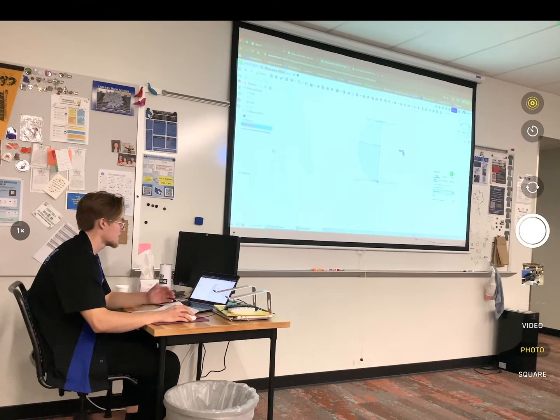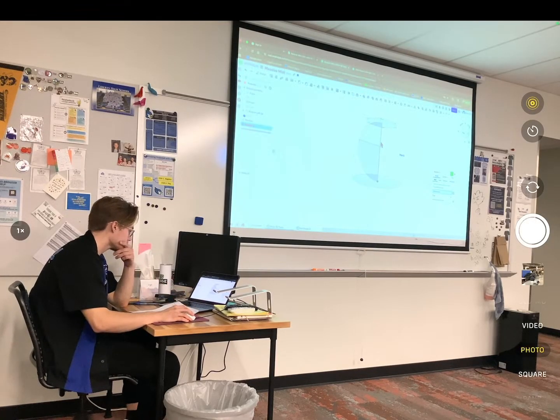I'm just trying to show you guys this. You don't have to make this part yourself. So with revolve, again, choose that sketch. Then that revolve axis, just like the mirror, I'm going to choose the axis which I want my sketch to be rotated around. So the moment I select that axis here, what's going to happen? It's going to go all the way around, revolve all the way through.